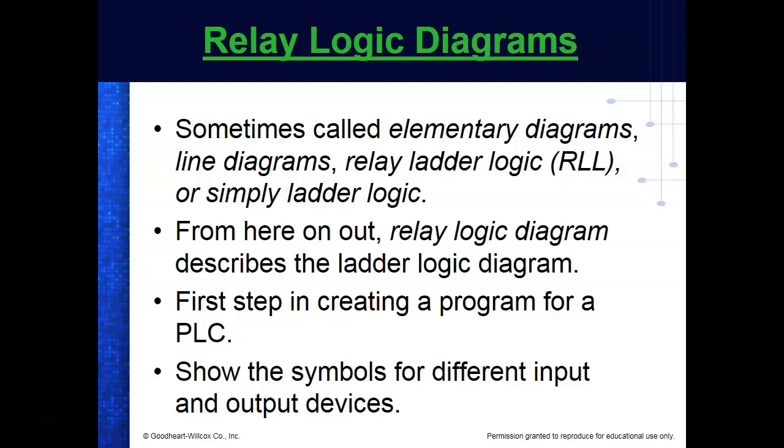Also, the starter on your car probably draws 70, 80 amps at least when it's warm, and you're turning it with a little key on the dash, or pushing a little button if you got one that's got a fob on it, and there's a relay out there. We call it a starter relay. We take that little 12 volts coming off the battery, and we hook it up to a coil, which energizes a relay, which can handle that current.